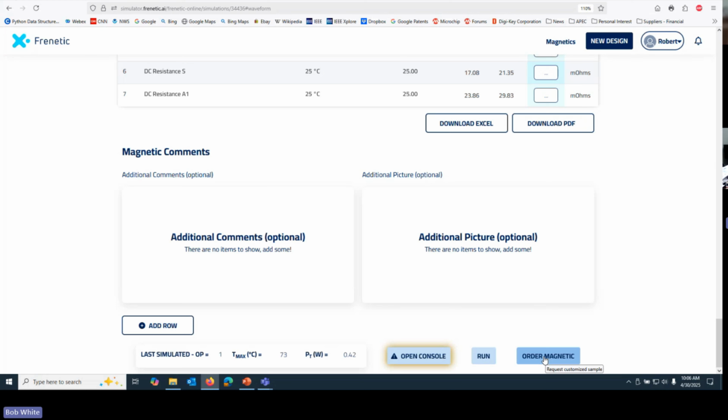Are there ways to recycle the leakage you would like to highlight? Well, again, that's a whole other world. There is something called an active clamp flyback. Much more complex operation, but it does kind of recycle that and give you a better efficiency than just the passive clamp. But that's a whole other discussion. But the active clamp flyback does recycle that lost power.